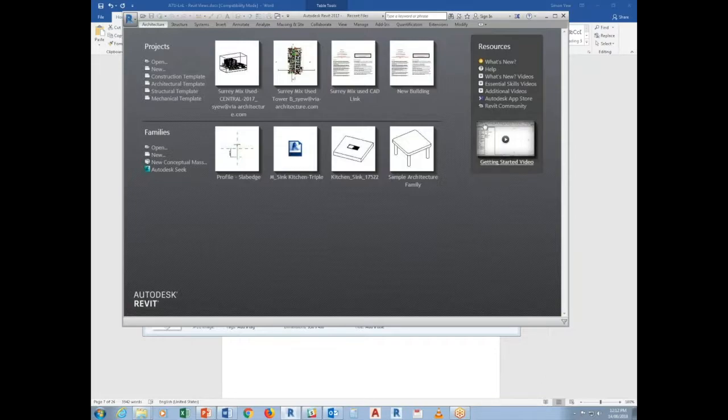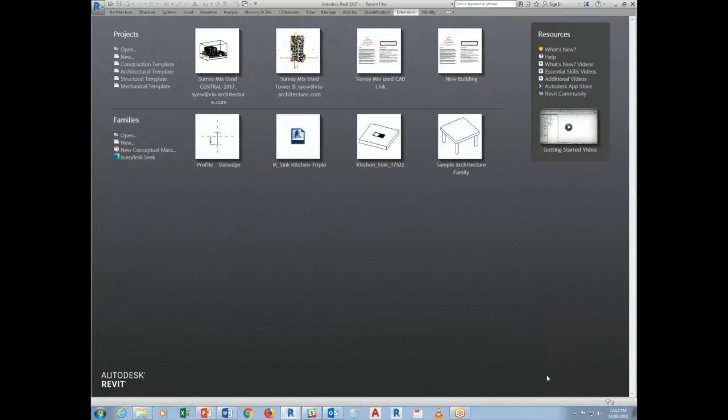To fix that issue, you have to get rid of the site designer tools that Revit puts in. You have to delete that, or else you will encounter this crashing more often. There's no chance to save, unfortunately, because once you close a project, it automatically crashes Revit. Autodesk has no fix, so they advise people to get rid of the site designer plugins, and then everything works.